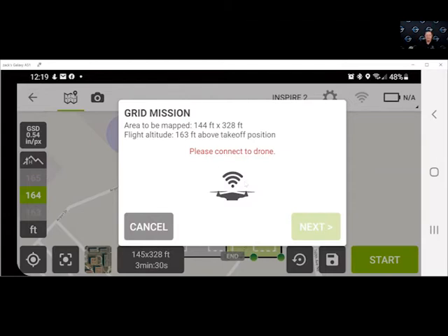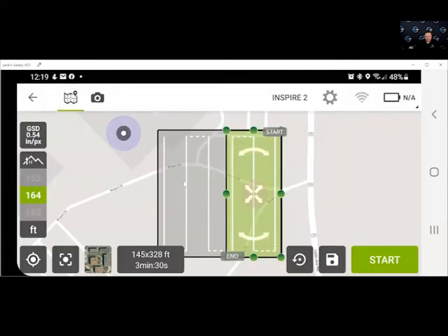It'll let you know whether or not there's an SD card, whether or not the mission was uploaded to the aircraft, any alerts as far as, well, you're starting this mission very far away, things like that. Making sure your switches are in the right place. You want to make sure that your switch is in P-GPS mode whenever you're doing this, so that way it's using your GPS for the waypoints. So yeah, it's a nice little checklist that comes up at the end.